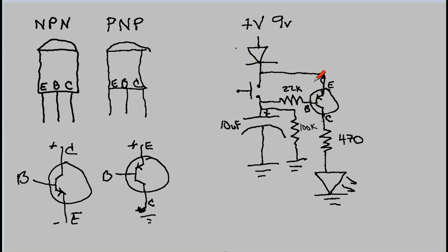So what happens is, the capacitor fills up. It puts voltage pressure against this switch, and then turns this off. And when we let go of the switch, because of this pressure here, and this light is off, it doesn't drain through here. If it wasn't for this resistor, if we didn't put this resistor in here, this would stay off. I won't say forever, because there is some bleed, but it would pretty much stay off for a very, very long time. You couldn't use it as a predictable element in your circuit.